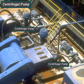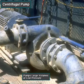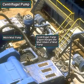The mud system normally has several centrifugal pumps. A centrifugal pump puts out relatively low pressure, but it can move a large volume of mud. Crew members, therefore, use them in several ways. One job a centrifugal pump often does is supercharge the mud intake of the main mud pump.